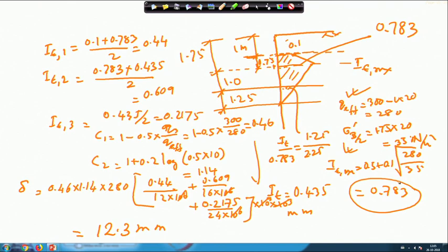Once I have got the I maximum, I have put it here, and then I know that for square footing and circular footing the strain becomes 0 at a depth 2b. So, 2b from base means how much it will be? It will be 3 meter. So, you can see this is 0.75, this is 1. So, 1.75 and then this will be 1.25, and so from the first layer, the second layer thickness is 1 meter.